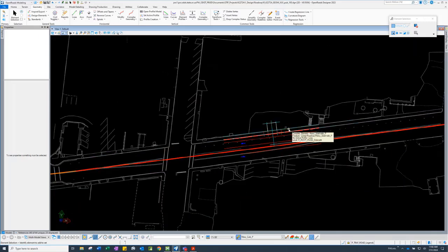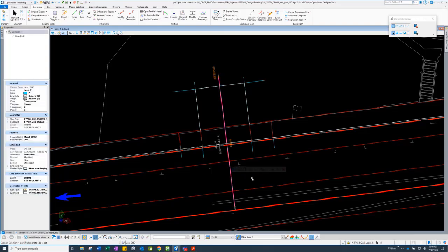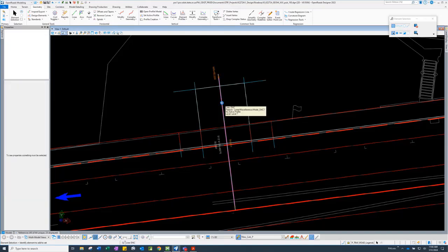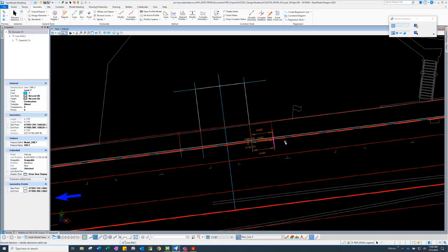So can I state this just again in another way? There are cyan blue colored lines that are the control lines. And she started with the center line of the driveway. So all of the other control lines are ruled to the center line. Maybe not directly, like the tiny cyan blue lines that are out at the brake line areas by the curb. Those are actually ruled to the next line toward the center line. But then when you check the ruling of that next line, it's ruled to the center line.